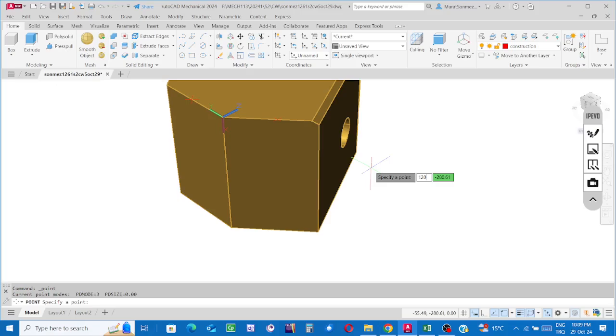You see, in this method, we write the coordinate values with respect to the origin, not with respect to the preceding marked point. No need to consider the displacement, whether it is in the negative sense or positive sense. We are writing the coordinates, location dimensions, using abscissa value. It is always positive. 120. Click on the comma key.